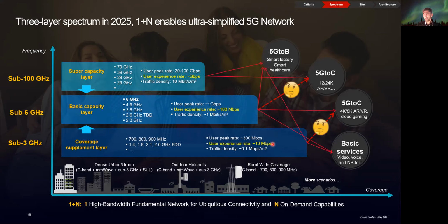So not all services are then possible to be delivered, but still we may enjoy, say, voice and video calls. But it's very, very hard to have a very high resolution transmission, which would require a higher carrier frequency, and therefore the possibility of having a larger bandwidth, or at least, I would say, a 100 megahertz band, so we can reach and sustain around 100 megabit per second, which would allow us to enjoy a different type